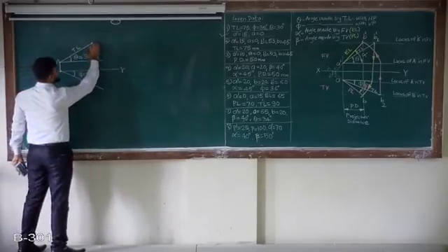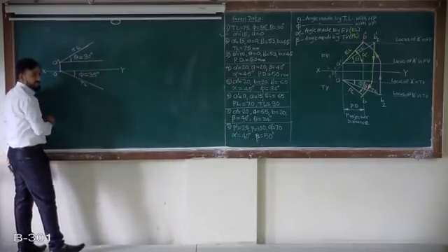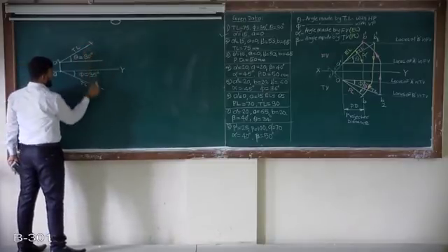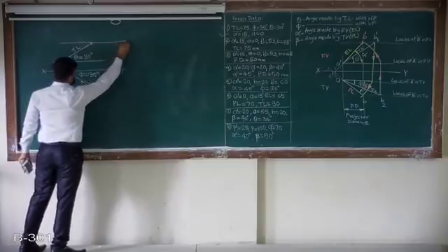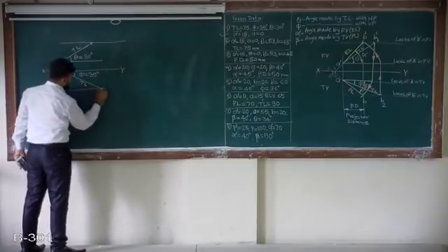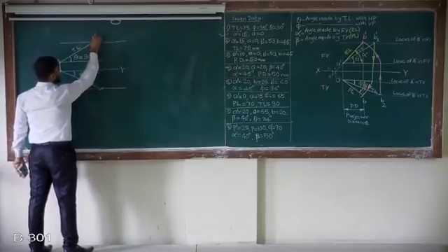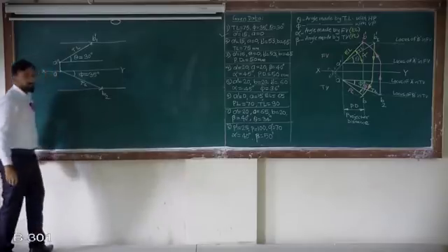Let us say the true length is 75. I will take 75 mm distance in compass, and mark from A dash and A on corresponding lines. So this point I'll get, draw the locus from this point. This point is B1 dash. This point I'm saying B2.